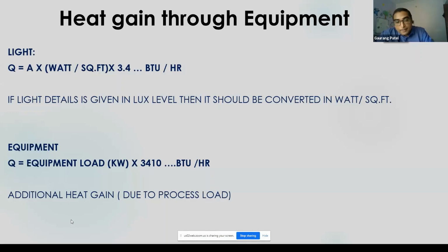If you have 4 kilowatt per rack or maybe 6 kilowatt, should they take 20% as heat gain, or should they take more than that? As I said, it is not like mechanical equipment, where only 20% comes as a heat load and the remaining is converted into work.